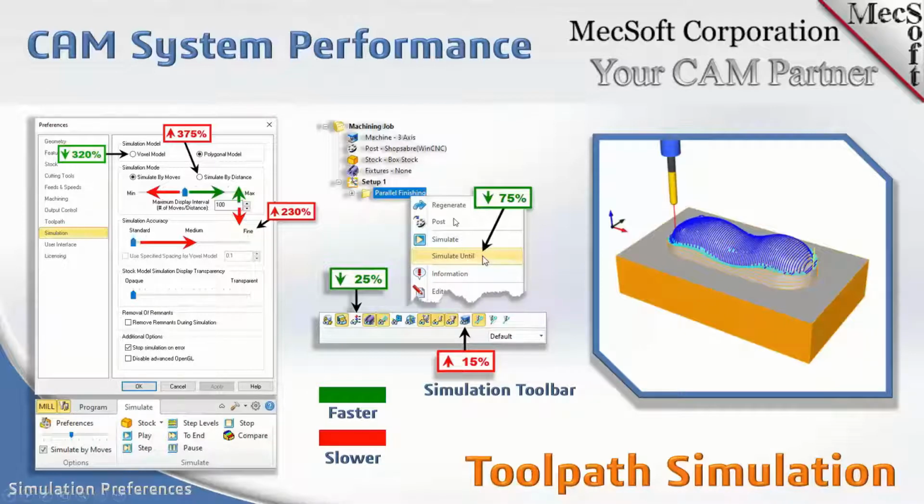Also be aware that if your operation is 12 operations down and you simulate until, it's going to calculate all the operations prior to that. It's not going to show them. It's just going to calculate them, get to the one you simulate until, and that's the one that shows on the screen. So in most cases, if you just want to see the simulation, just pick simulate until, and it'll bypass all this other stuff if you don't want to worry about it.